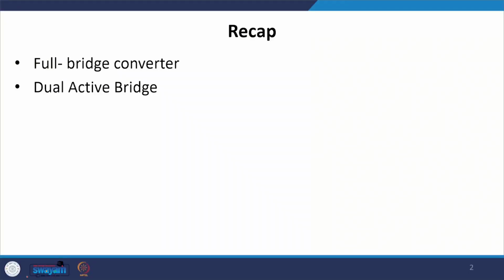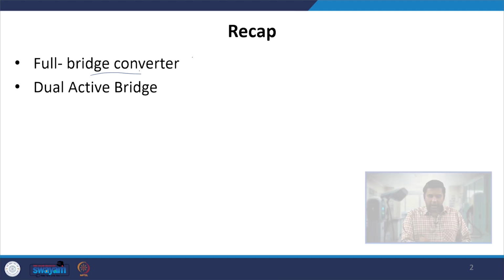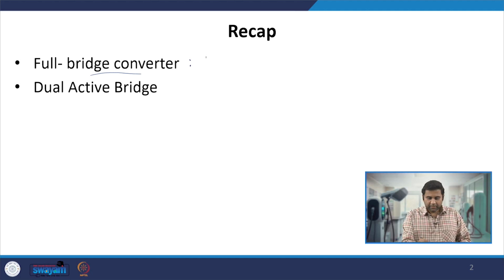If you recall, we have studied in detail the full bridge converter and its operation, and then we saw the different PWM methods possible with the full bridge converter. Then we saw the phase shift full bridge converter, its different modes, and its conditions for soft switching, that is, zero voltage turn on of the switches in both the leading and lagging leg, which we discussed in detail.